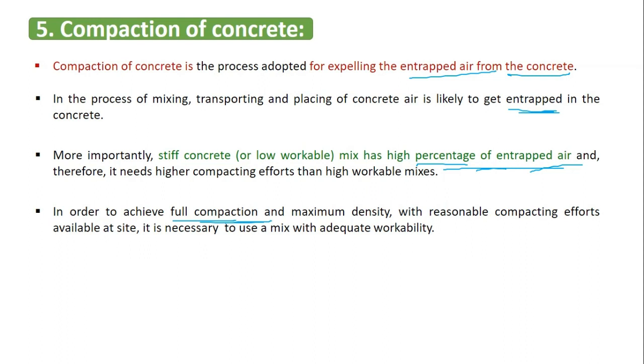It is important for us to understand that full compaction of concrete is necessary to achieve maximum density and maximum strength. Unless you do a full compaction and remove all the entrapped air, you cannot get a maximum density concrete, so you cannot fully achieve the strength of the concrete. So you need to get a full compaction and a maximum density concrete.